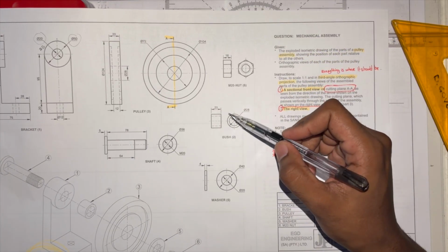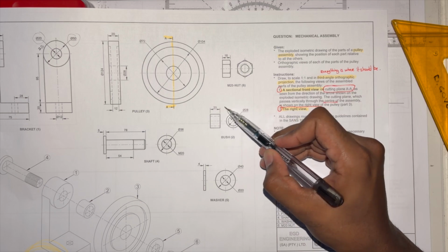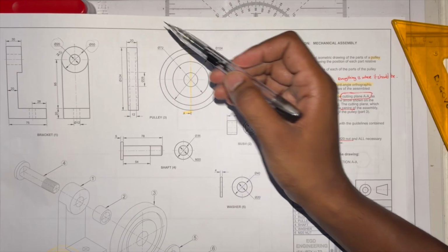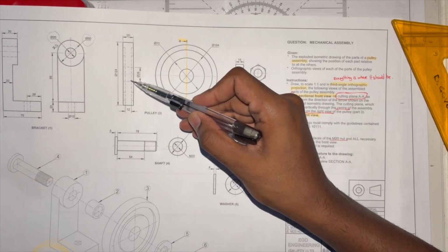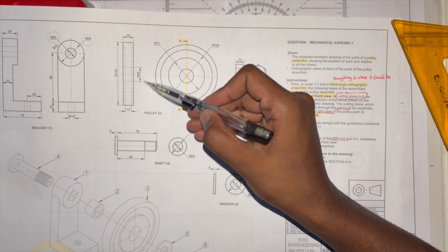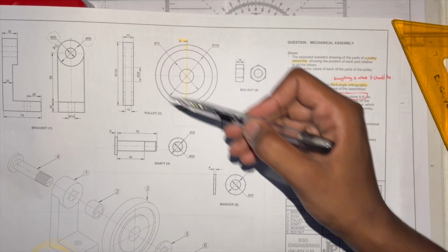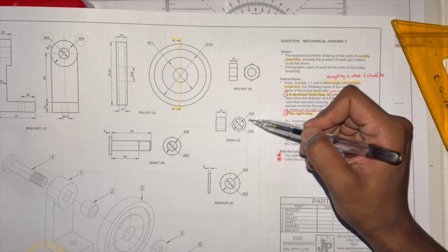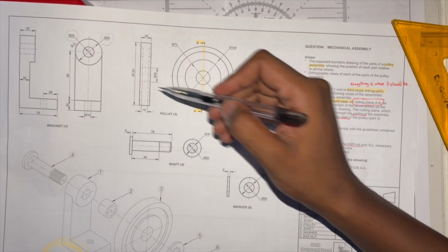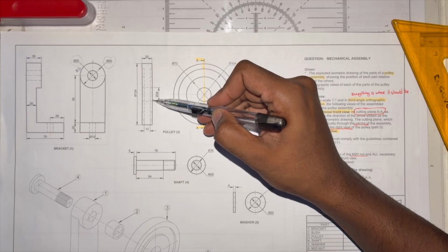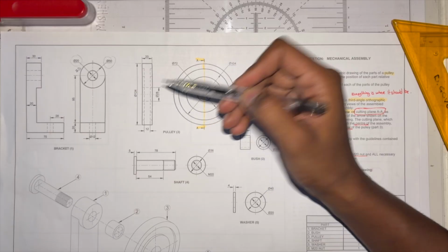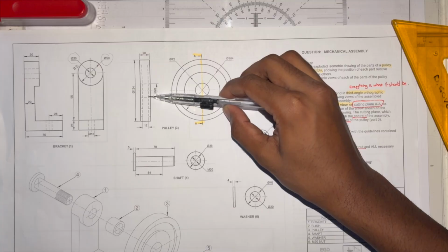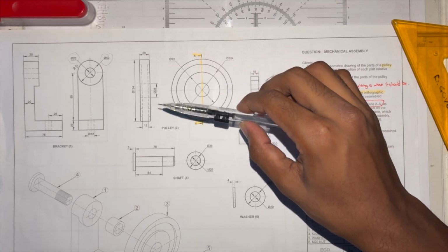One of the clues would be the diameter. If you look at this length, it's 20. If you look at the length of this pulley, it's also 20. So perhaps this bush goes into that pulley and not sit flush on the outside, because that's 20 and that's 20. Now let's look at the thickness. The outside diameter of this bush is 28. The inside of this pulley is 28 as well. Is that a coincidence? No. I think that this bush fits perfectly into that pulley. That's what I think. So it should be done like that.